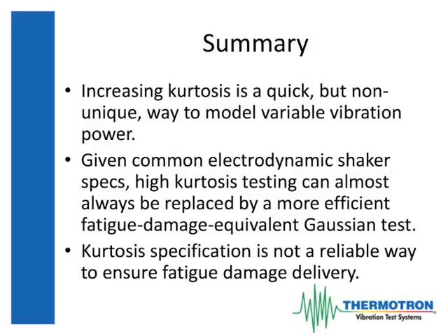If you are running on an ED shaker, I think it's safe to say you can always replace high kurtosis testing with a more efficient Gaussian test that does the same fatigue damage in less time. And using kurtosis as a specification is not a reliable way to get the damage that you want to validate your product against.